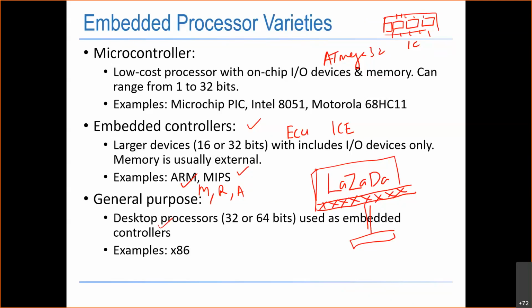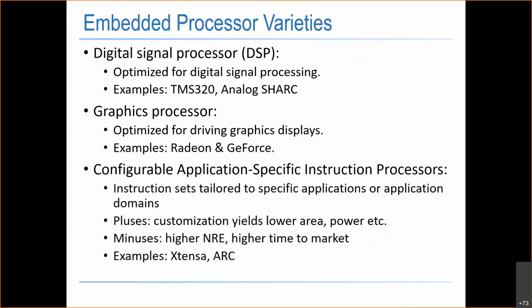Obviously, if you want to drive a big LCD display like this notice board, you can't really use an Arduino board. You can't really use an 8-bit microcontroller because it's just too slow. It doesn't have the required peripherals to do that. So it really depends on the application, but you have the choices of going all the way from microcontroller to embedded controller and to a higher performance general purpose processor, depending on your application.